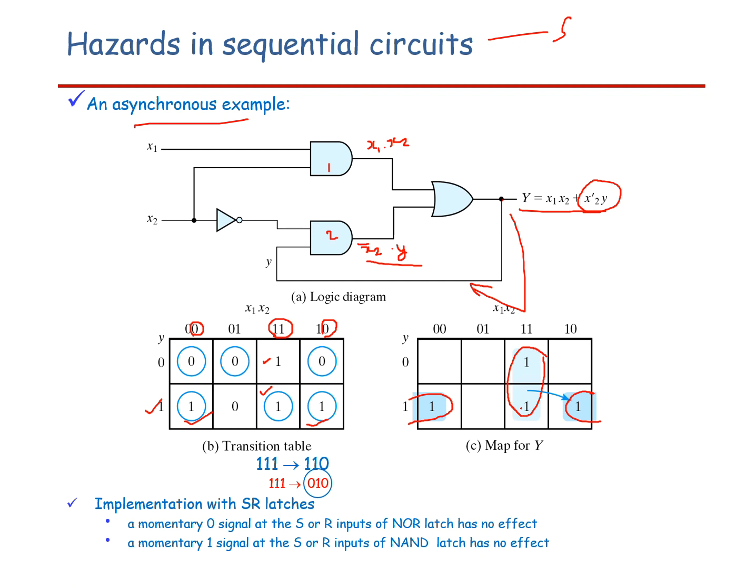Here you can combine these two ones, which means that there exists a hazard during this switching, when x2 switches from 1 to 0. When x2 switches from 1 to 0, there exists a hazard. Hence, we need to group these two ones to form a redundant group. This is done simply by adding a gate to the asynchronous circuit. This is one way.